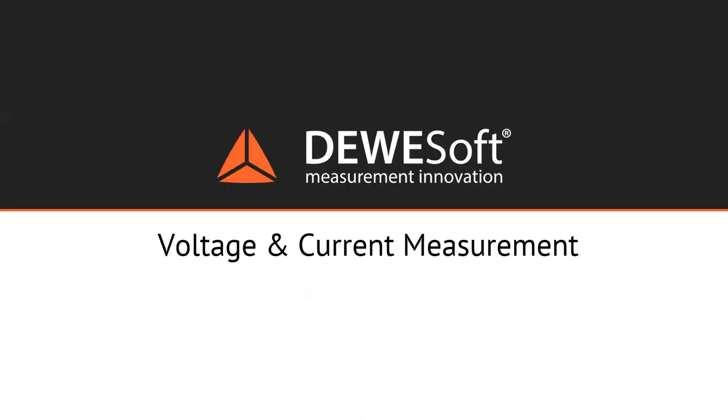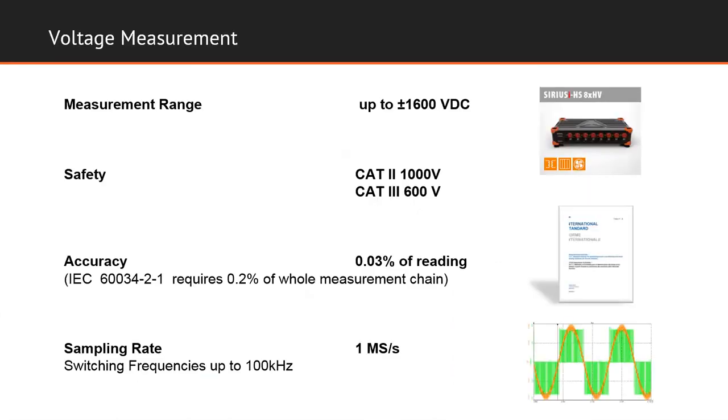Then let's talk about voltage and current measurement. We've talked about the measurement range. This is up to 1600 volt DC. We have the safety category 2 1000 volt and category 3 600 volts. We have the accuracy of 0.03% of reading.